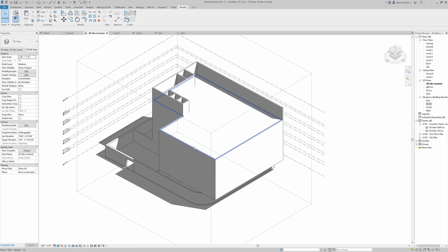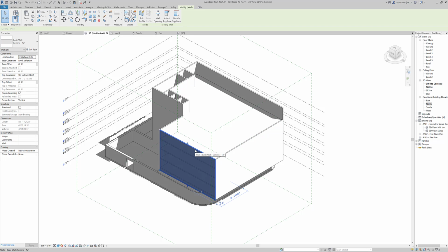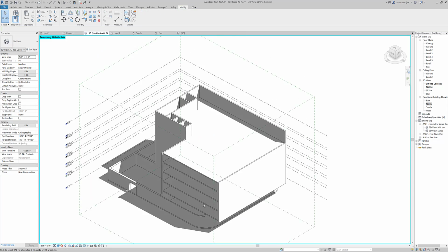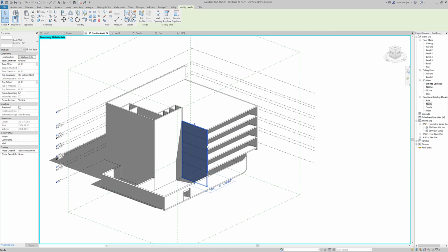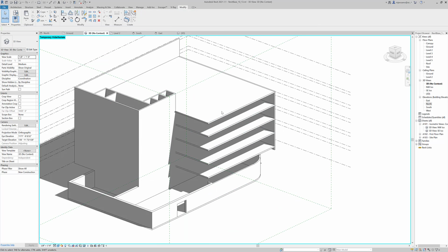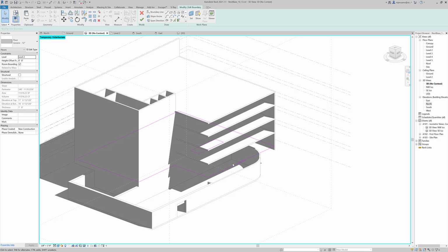plan. So lastly, I'm just going to show you again how to change the sketch of this element, and I'm going to hide this wall here temporarily, so you can see that if I didn't want this to go all the way out, right? I want some light in this lobby. I can double click this, and I can actually do something like this, where I trim and I fillet the elements together.